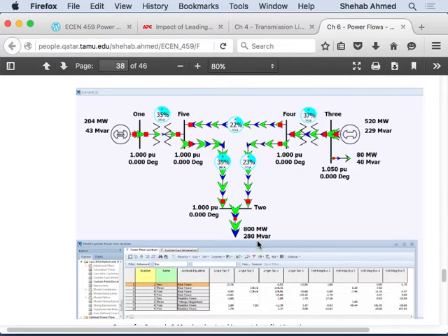Exactly, it's generating reactive power locally for that induction motor, meaning the reactive power is not coming through the line, meaning there is no drop across the line due to the line's inductance. So what the capacitor did was play with the voltage. It allowed the voltage not to be dropped across the line between the generator and the load.